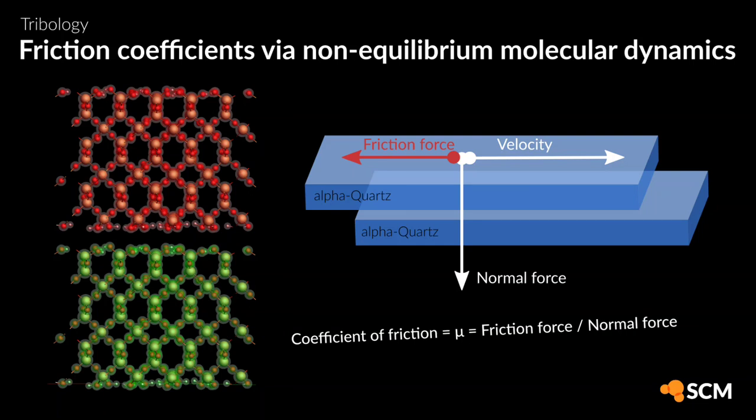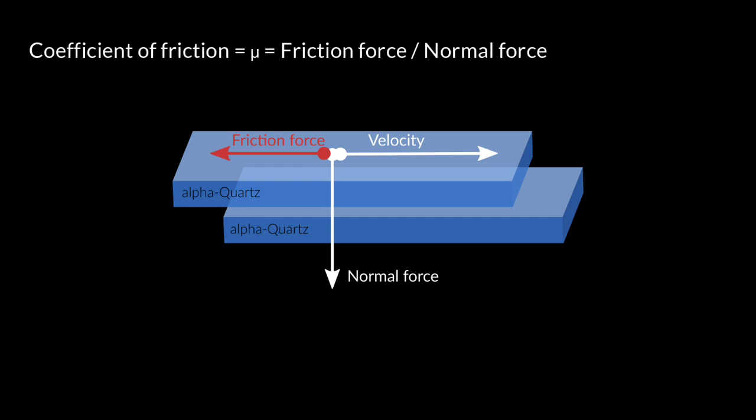Non-equilibrium molecular dynamics, or NEMD in short, is a commonly used tool to study phenomena like friction and wear in tribochemical systems. In today's video, I want to show how to set up an NEMD simulation to calculate the friction coefficient of two sliding quartz surfaces with the reactive force field ReaxFF.